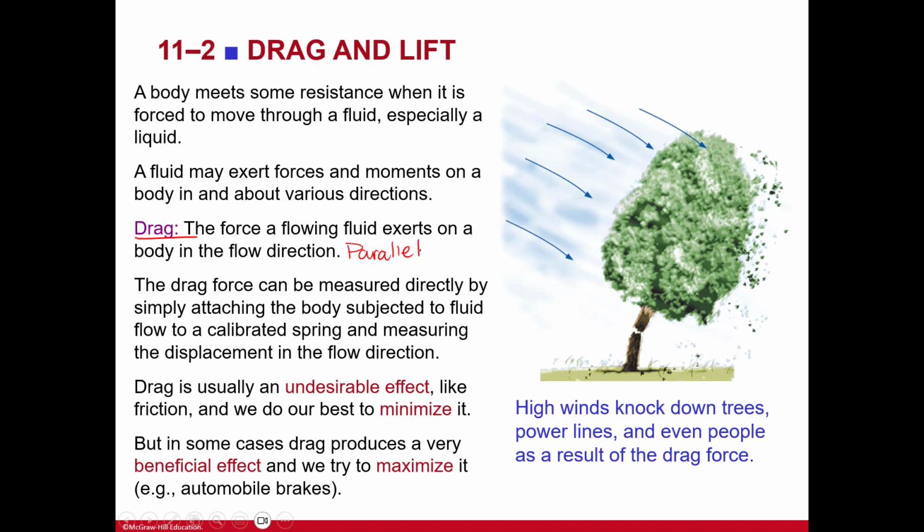Drag force can be measured directly by simply attaching the body subjected to fluid flow to a calibrated spring and measuring the displacement in the flow direction, and that's because it's parallel. Drag is usually an undesirable effect, like friction, right? This can be equated to friction, not from a calculating standpoint, but from a symmetry standpoint.